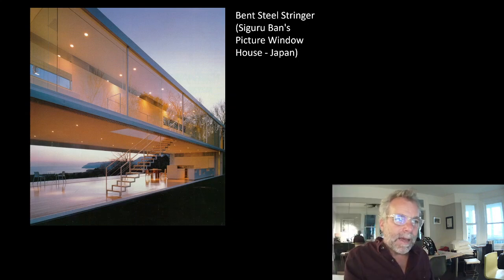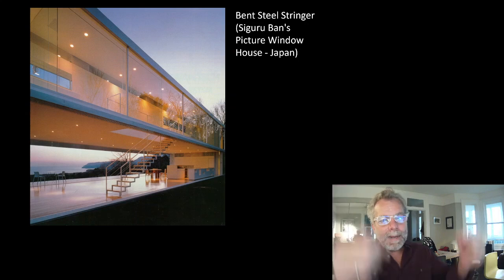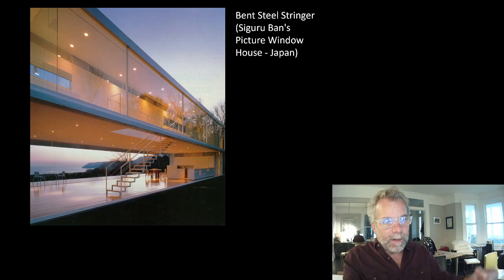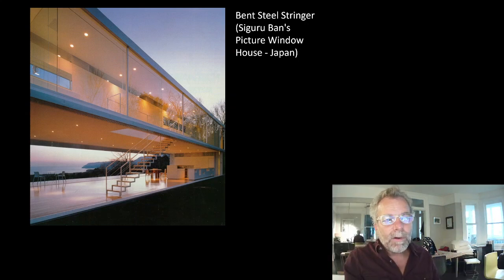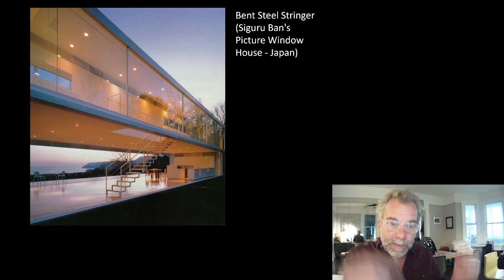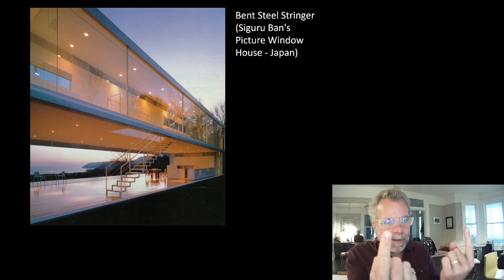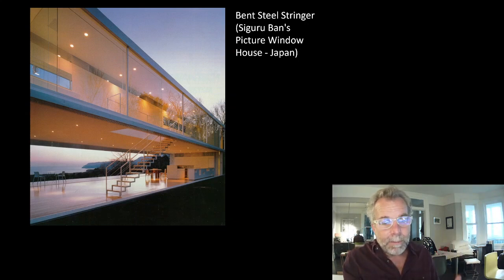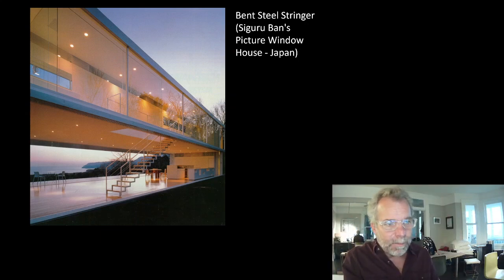So we derived a cambered shape, and then at mid-span we had tension rods, and we preloaded it down. You weren't aware of the fact they were tension rods, so they're very, very small. You didn't perceive them as supports, and from a strength point of view they weren't, but from a stiffness and vibration point of view they acted as supports. They had the same impact, so that it became a rigid stair.